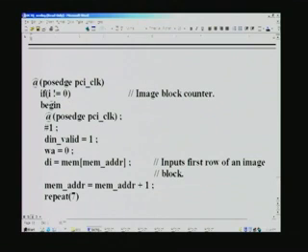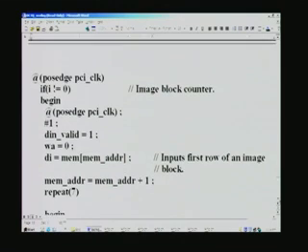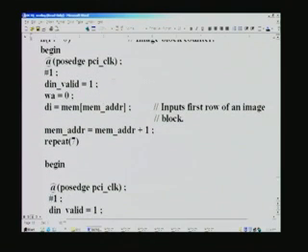Because I was initialized to 1024, block after block it will be decremented and checked here. At the positive edge of the clock we make the data invalid, because we are going to input the very first block, which can be got from the memory where, using readmemh, we have already stored the disk file.